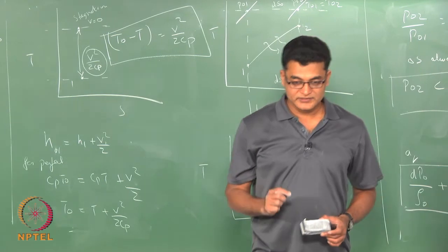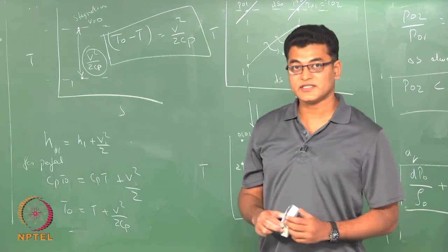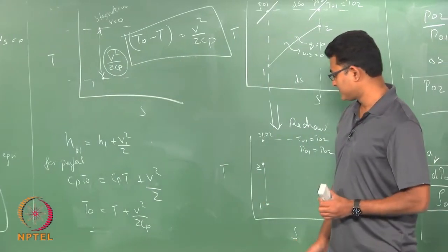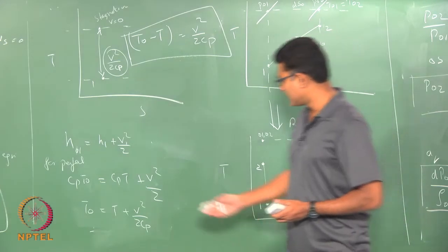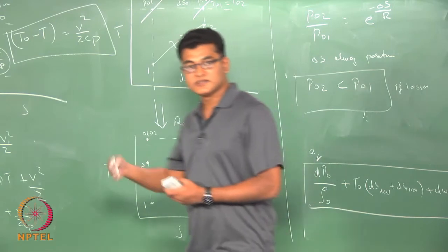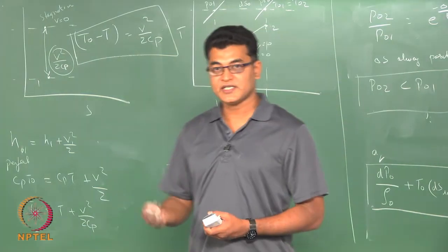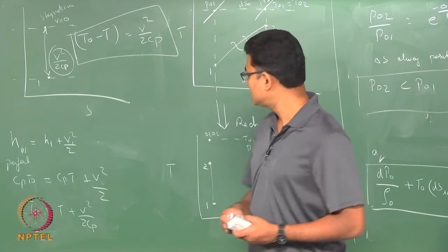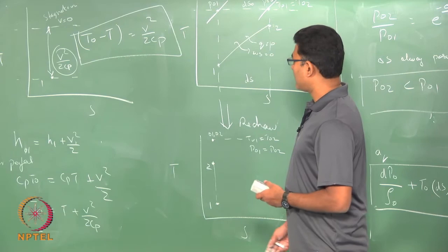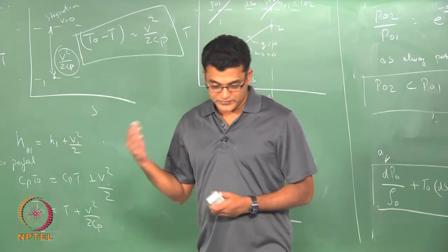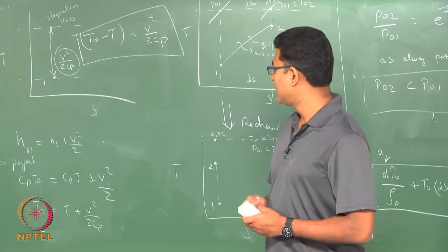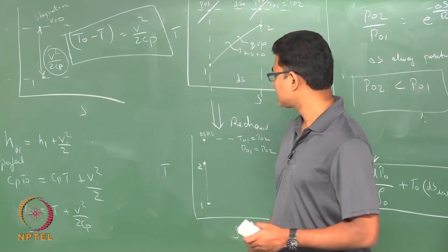What we have learned today is the concept of stagnation condition, the possibility of a new quantity, a stagnation temperature, and associated with it a stagnation pressure, and hence other quantities as applied to your energy equation as well as your ideal gas equations. Those relations are derived from your thermodynamics laws, energy equations and Gibbs relations.